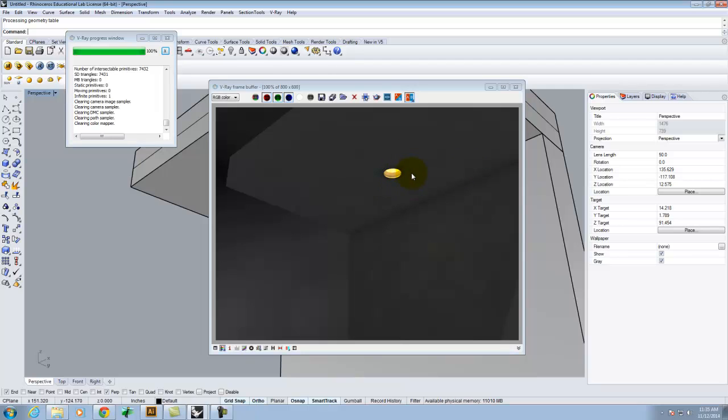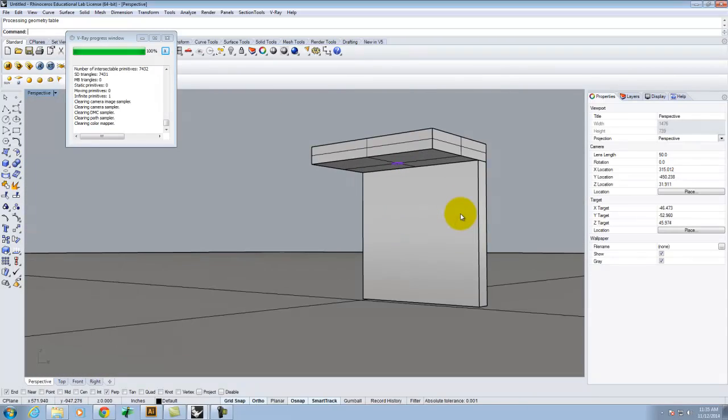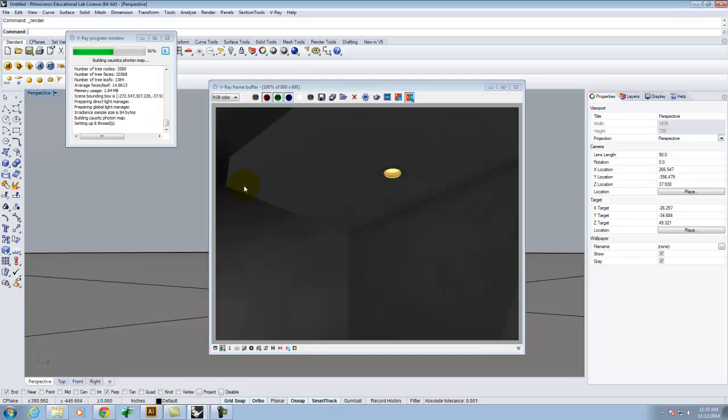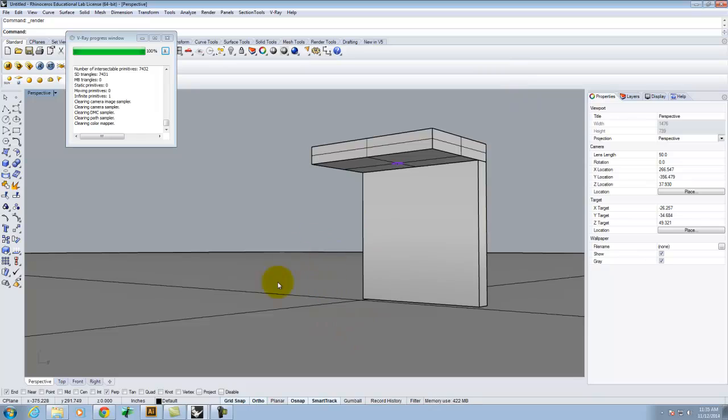It looks pretty good. But if we look at this scene from further away, let's say we're looking at it from right here, and I were to render it, there's a little bit of splotchy light on the back wall, but there's really not much other than the bulb itself. So we need in this scene to actually apply and cast some real light, some V-Ray light. So what I'm going to do now that I'm in the actual scene, so this is not done as the block, this has to be in the actual scene that you're going to render, I'm going to insert a V-Ray light.